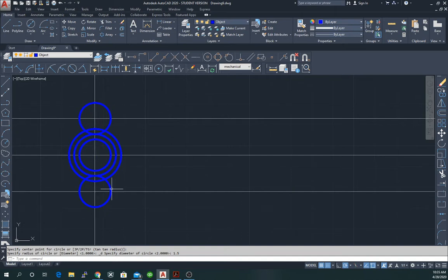And if you look at the call out for the mounting hole, you see a diameter symbol of 3/8, and then this kind of U box symbol, diameter 5/8, with an arrow pointing down, and then a 1/8. So what does that mean? That means that you have a hole that's 3/8 inch diameter, and that's the center hole, and then you have a counter bore with diameter 5/8 and a depth of 1/8 of an inch.